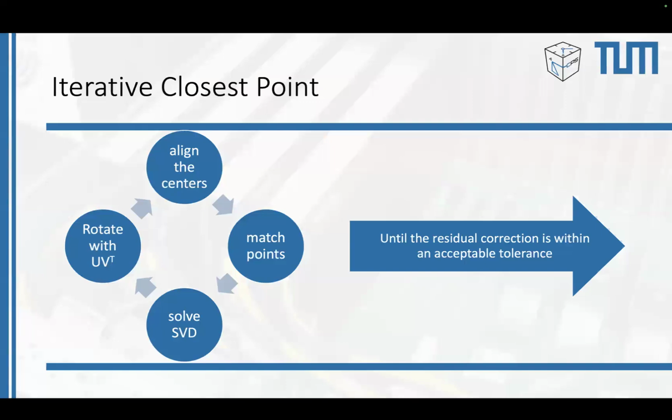So far we have just spoken about the rotation, but I have another problem. I need to bring the model to where my sensor has discovered this object, right? So the first thing I want to do is align the centers. I have some data here. I want to bring my model here, and then I first rotate it. When I rotate it, I match the closest point to each point of the model, and from the sensor and vice versa. So I match points that are nearest to one another.